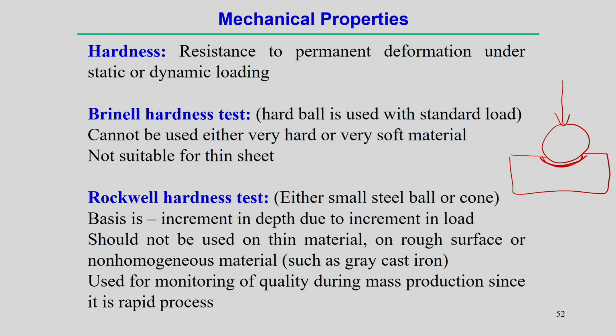Now, this Brinell hardness test is normally not applicable when the material is very soft, and at the same time it is not applicable when it is very hard. And of course, for very thin sheet this hardness measurement technique is not suitable. We can look into the other hardness testing methods also.